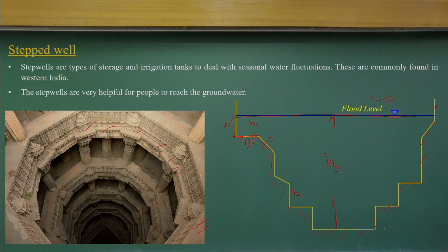For a horizontal surface like the one here, it is very easy. If I have a fluid of density rho 1, and the height is h3, the pressure at this point is P atmosphere. You know it, the pressure at this point will be P atmosphere plus rho g h3. And the pressure distribution will be uniform as it is a horizontal surface.